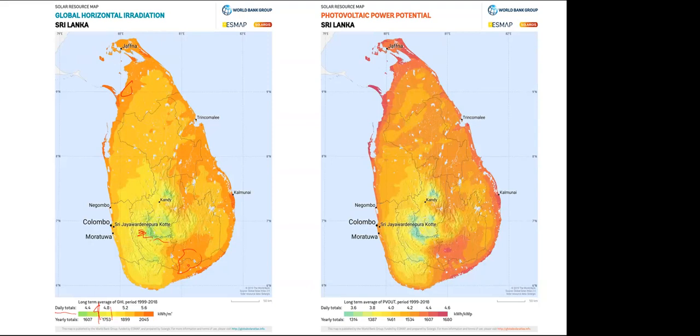Yes, some countries, because you may now know about energy curtailment. In Sri Lanka, we are not using a smart grid. Some countries are using smart grids. Solar PV and wind can be curtailed. That means the grid has the facility to control that energy generation by solar and wind, because if the grid cannot absorb that amount of energy, the smart grid can curtail those power stations.